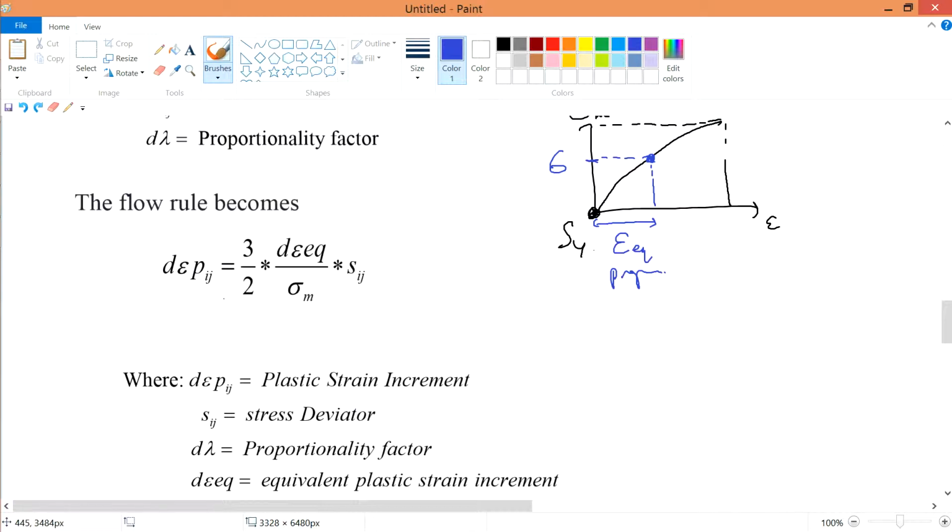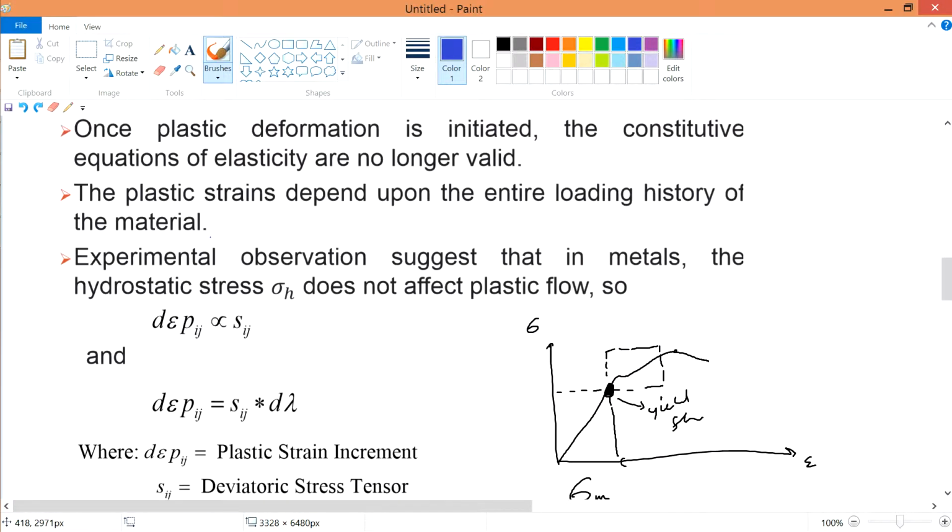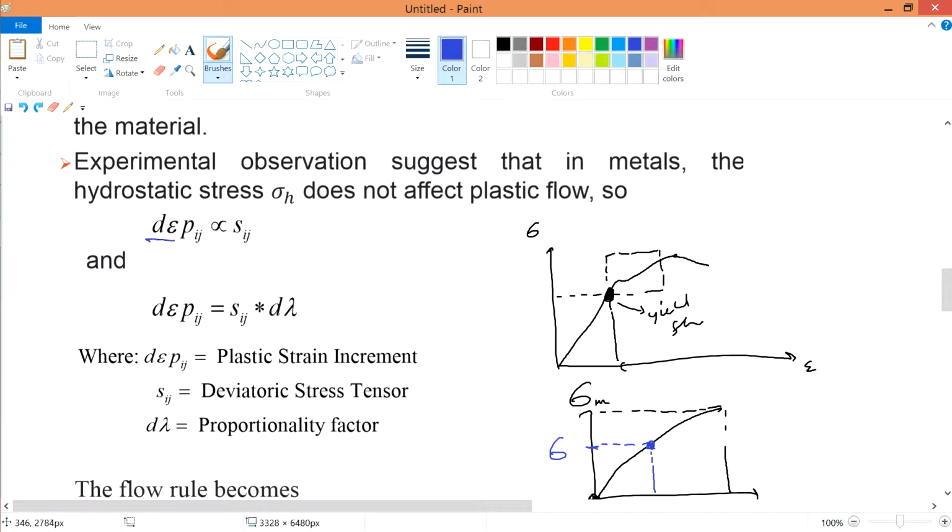So this is a very key understanding, although we can't see it over here, I don't know why. But still, at least you know that this is some strain increment. How do we derive this? The small strain increment, when you input a certain stress, is with regard to the deviatoric stress, where if you subtract away the hydrostatic part, you get some values, maybe 3, 4, 5, because of symmetry.